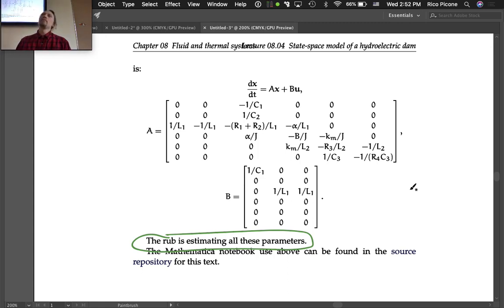If you can't, though, which is often the case, you have to do some measurements yourself. And you can, for instance, put a pressure measurement device on one side of the screen and a pressure measurement device on the other side of the screen, and also measure what the flow rate is that's going through the screen. If you measure those, the ratio of those is going to be the resistance. So that would be a way to estimate your resistance going through the screen.